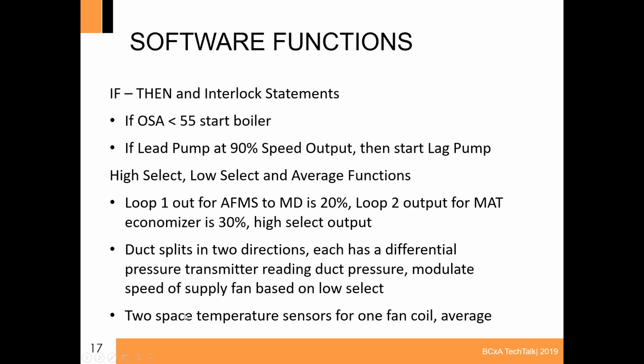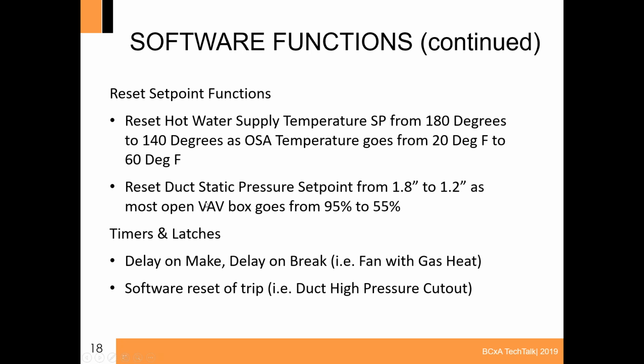You might have averaging where there's two space temperature sensors, like for a gymnasium. Gymnasium's a really big space. You might have a temperature sensor on each wall, and you're going to take an average of them to determine space temperature. Okay, more software functions, reset functions.